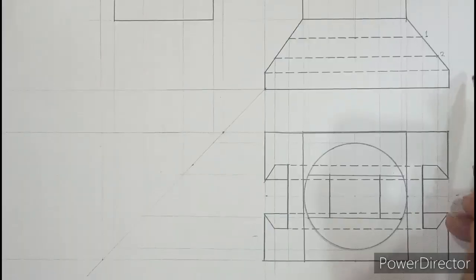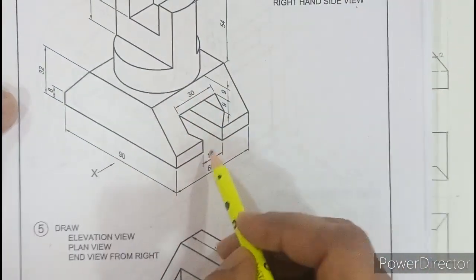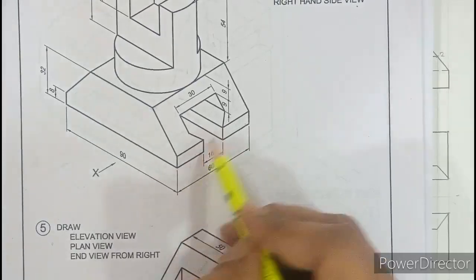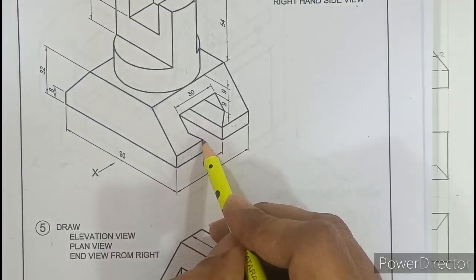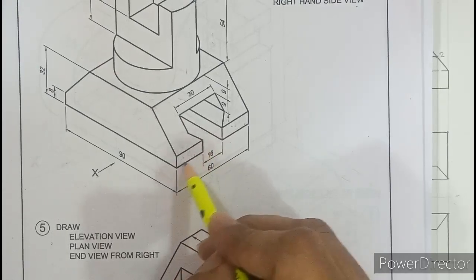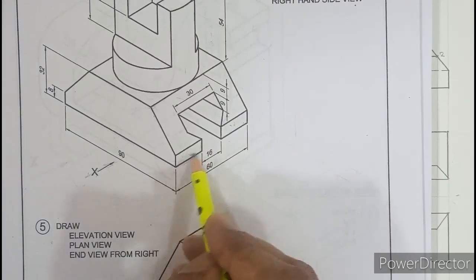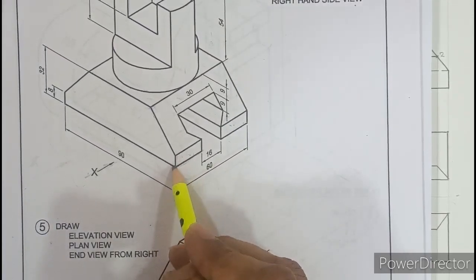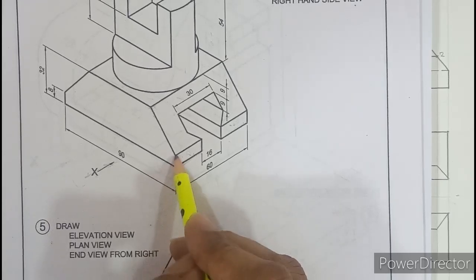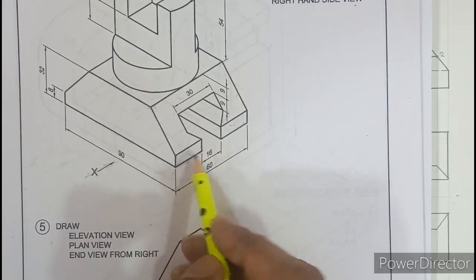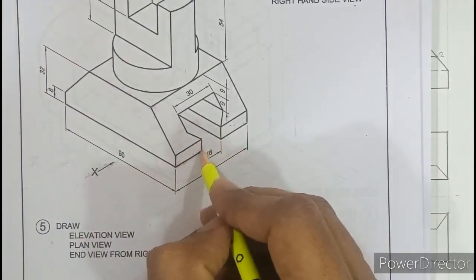Now when we start with the side view, let us try to draw first of all these two rectangles. To draw these two rectangles, one must know the height and the width. When you look from here, this is the length, so this has to be the width. In the side view you can see width and height, correct? The height of any surface you always get from the front view and the width you get from the top view. So we just need to find out where this height of 8 mm is in the front.